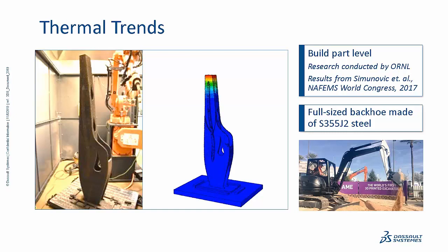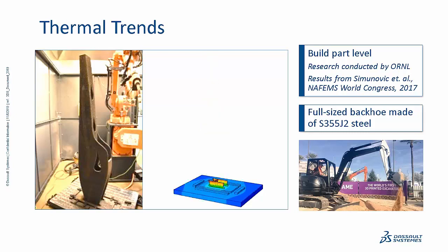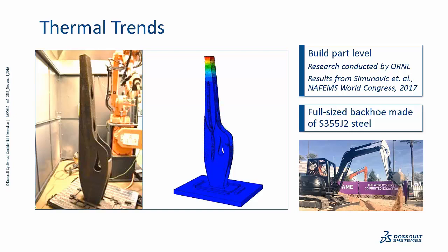In this case, they did not instrument this print, so we only conducted thermal analysis. That is, no validation work, but qualitatively they agreed with what they saw from the virtual print thermal result. The simulation job took a few hours to run, so considering 4.6 days for real print and its possible print failure, simulation of virtual print provides a clear incentive in replacing the physical trial print of parts like this if the simulation tool is predictive.